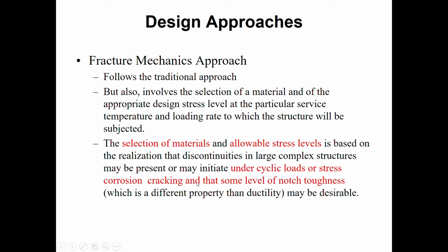We involve some kind of iteration for us to predict what is the geometry that we need to apply within the structure using this fracture mechanics approach.